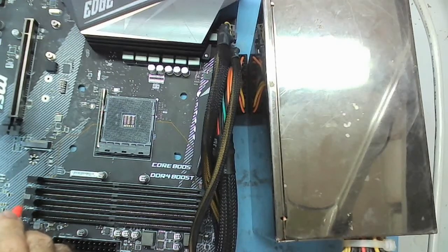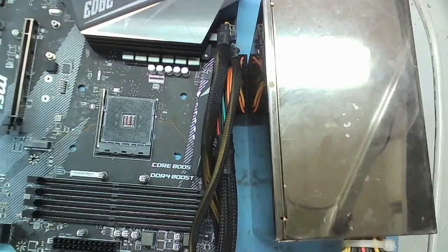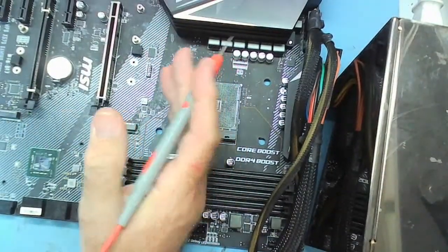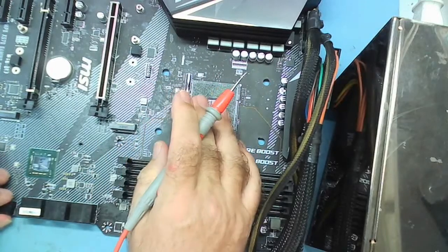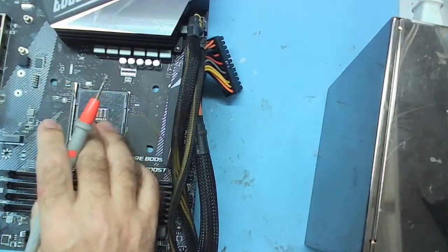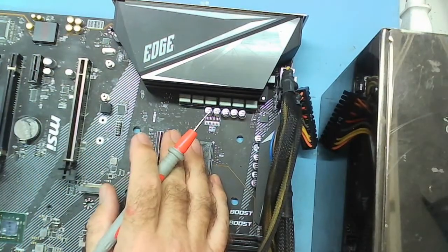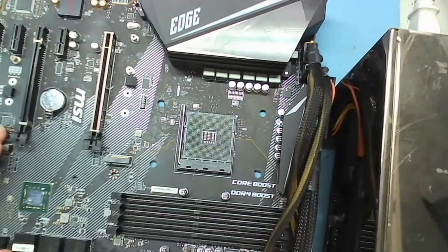We'll change that chip, and then we'll see if it works. If we get the right voltage on here, I'm confident this will power up. If it powers up, we can try the CPU and get it to run. We can try the post analyzer card and see if that works. If we get this one running, then we'll have another look at the other one to see why that one isn't running.